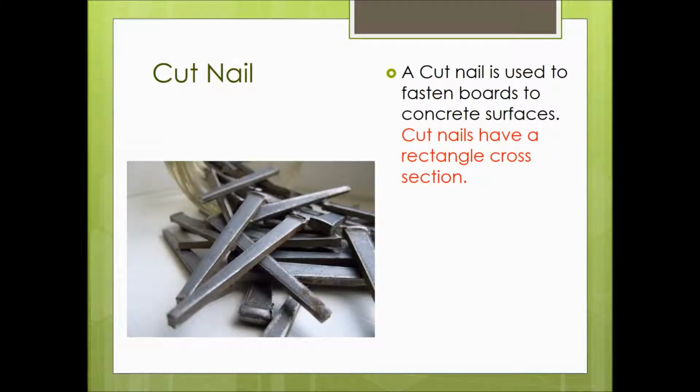Okay? These are cut nails, and they have a rectangular cross section, and they are used to fasten boards to concrete surfaces. So you can actually take this nail and drive it into concrete. If the concrete's really old, you're going to have a pretty difficult time driving it into that. But if the concrete's just a few days old, you can drive it right in there with the regular hammer, no problem at all.